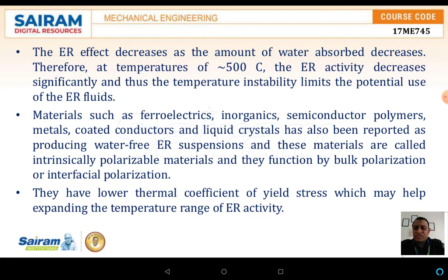Materials such as ferroelectrics, inorganic materials, semiconductor polymers, metal-coated conductors, as well as liquid crystals have also been reported as producing water-free ER suspensions. These materials are called intrinsically polarizable materials, and they function by bulk polarization or interfacial polarization.